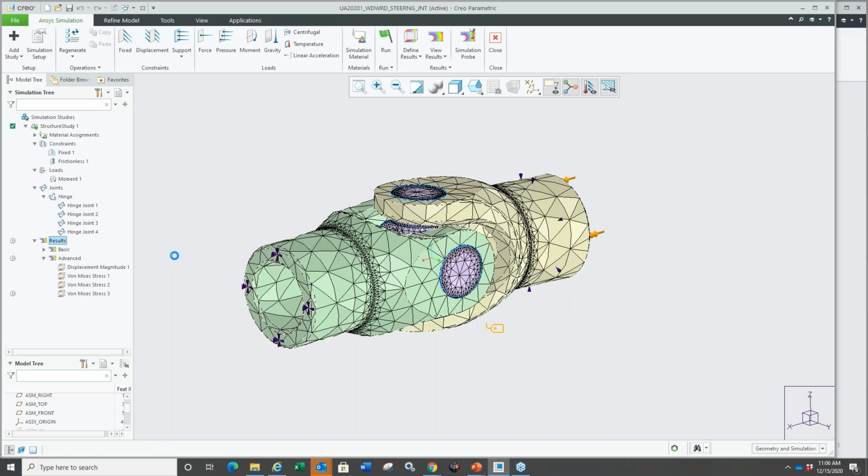In fact, instead of doing this every time, I could just save this as a template, and you could also view results from template. Very, very useful tool actually. So that each time you're not doing this manually, you run the analysis and then say show results from a template that always loads the things that you want. So that's another option there.